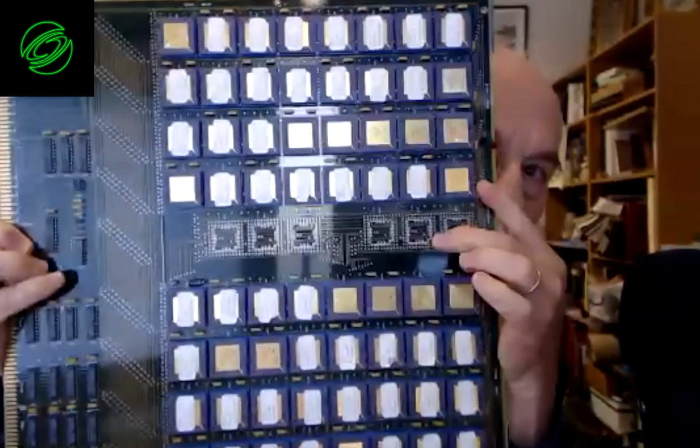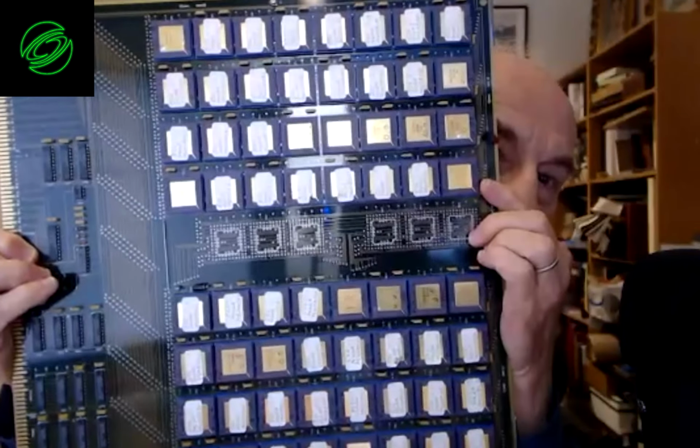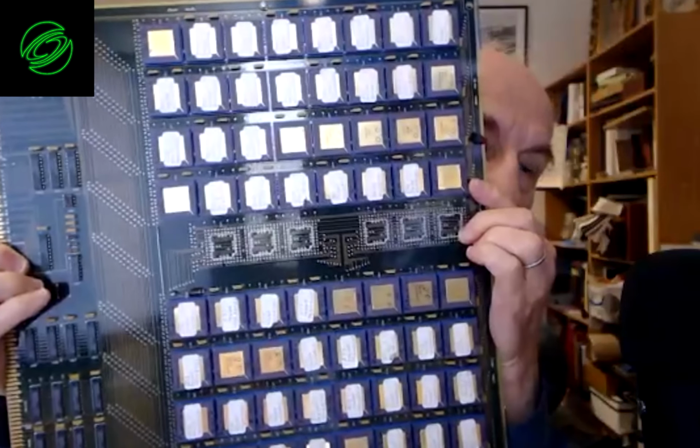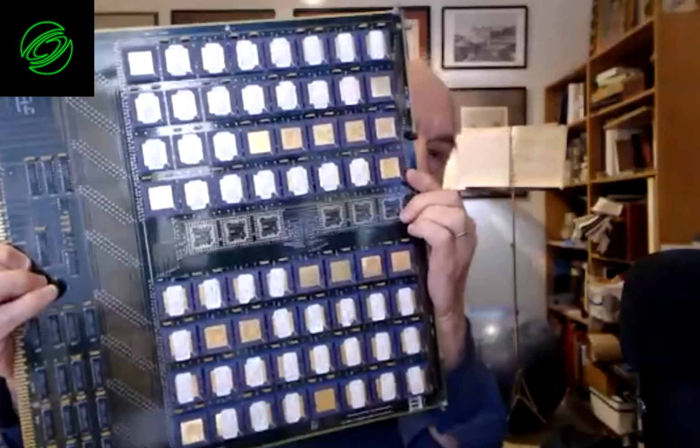We needed 2,000 working chips, and we didn't think that we could get that many that were perfect. And so we spent a lot of time on how the system could handle chips that would have one or two errors somewhere in the memory or the processor or the tree. And if you look carefully at the boards, you'll notice that there's a whole row which is not populated. That's because we thought that we would need that many more chips, with one fault here or there, in order to have a 512 square system.